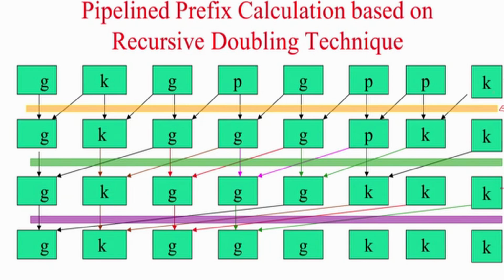First set of data comes to stage 1, you compute that and store the results here. And you also take along with it your A's and B's, you just keep propagating. So this not only stores the result of this computation, but it will also take along with it the A's and B's. Now when stage 2 is computing the results of stage 1, I can bring in another set of new numbers.